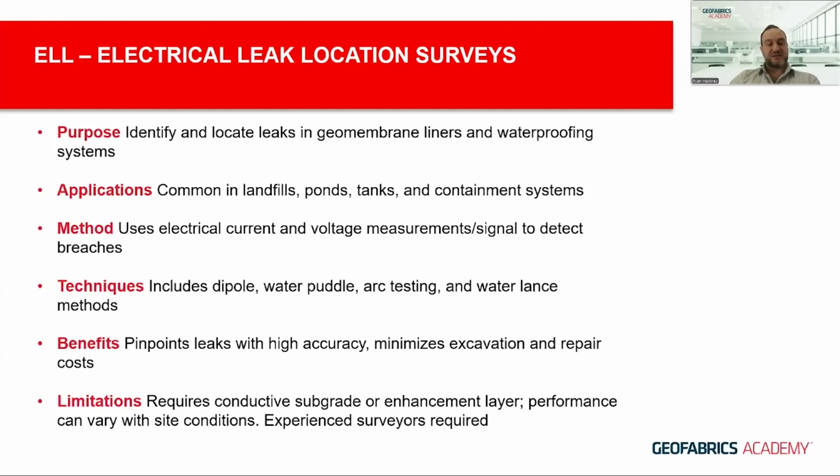So it's key that experienced surveyors that understand the methodologies are used, and they can then calibrate the system or the survey according to the specifics of the site itself. What works on one site may not necessarily be the same procedure on another, just due to the local conditions.